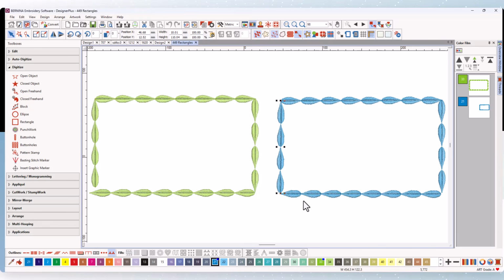That's going to give you greater control to either increase the length of the line a bit or decrease it or move it a little bit, maybe increase the size of the stitch, and you can get a better frame that way. So just be aware that if you have a gap that you don't like in your pattern, rather than trying to figure out the spacing or resizing the rectangle, you can easily digitize 4 straight lines that come together as a rectangle.